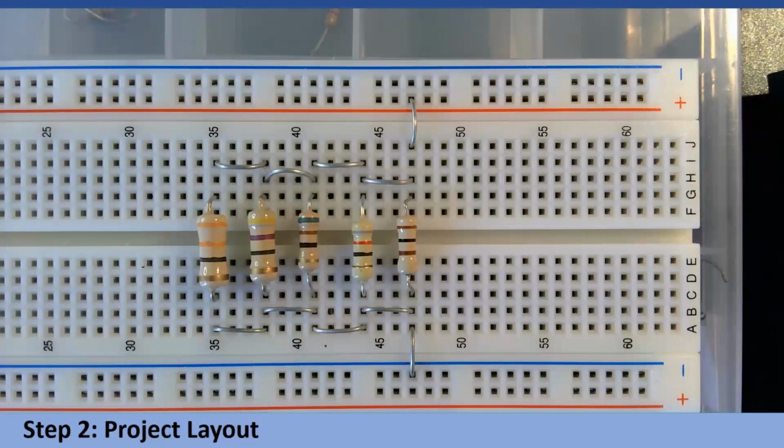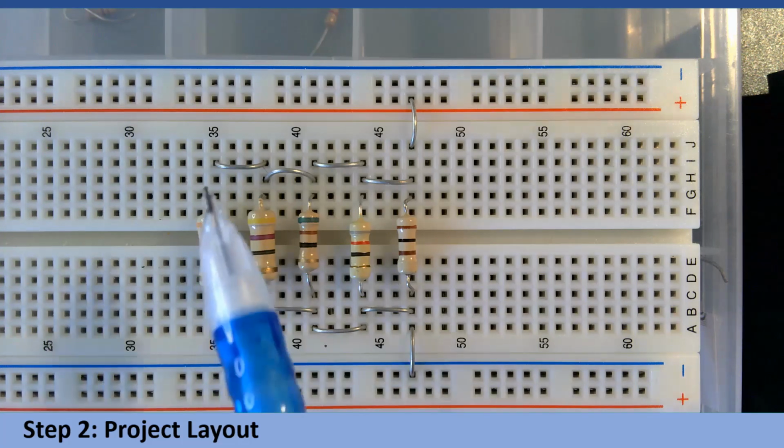So for Lab 2, we're going to use the same resistors we used in Lab 1. We're using a 33 ohm resistor, a 47 ohm resistor, a 51 ohm resistor, an 82 ohm resistor, and a 100 ohm resistor. I've laid the board out with these jumpers in the same configuration we used in Lab 1. This is to create a series circuit of no resistance. Basically the same as a wire. I've done the same on the other side.